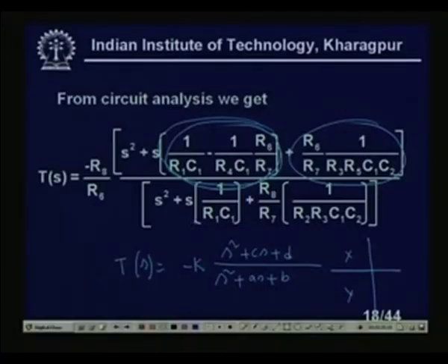Its sensitivity is also quite low, and its tuning is a great advantage. You can see in the next slide what different elements we can choose to tune omega p, QP, omega z, QZ independently, right. Because as you know, in the filter parameters we have to tune omega p.